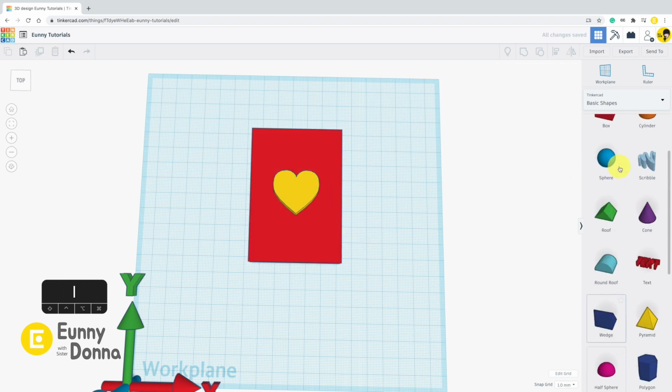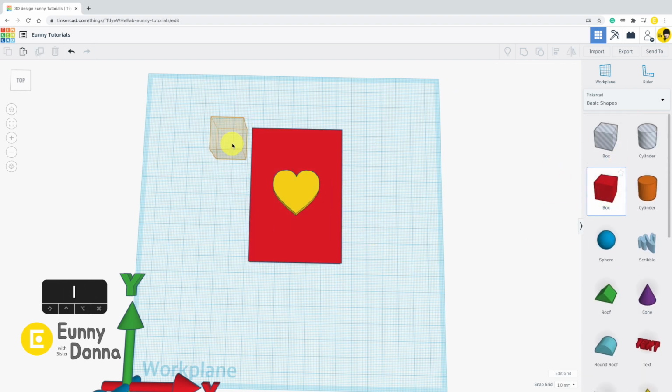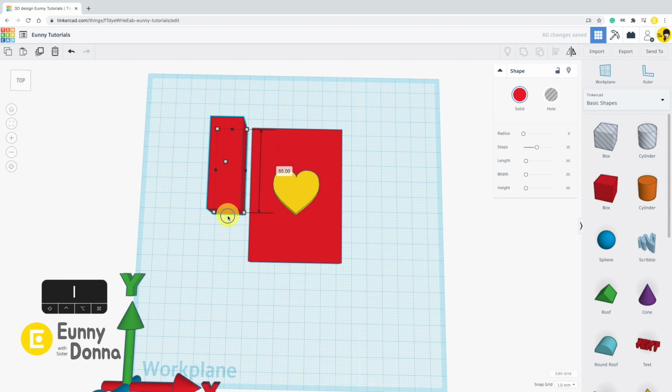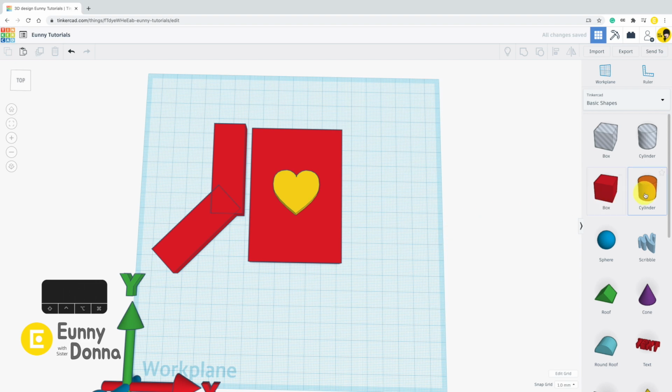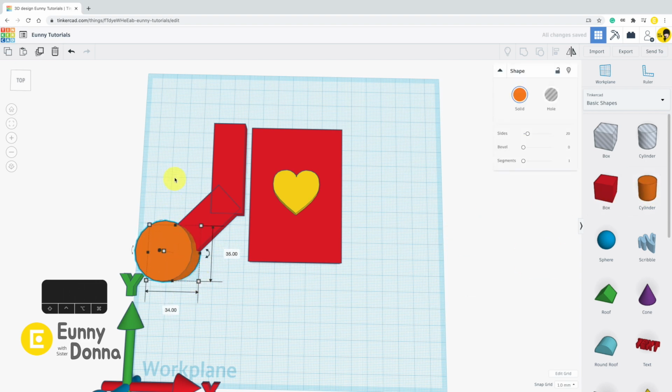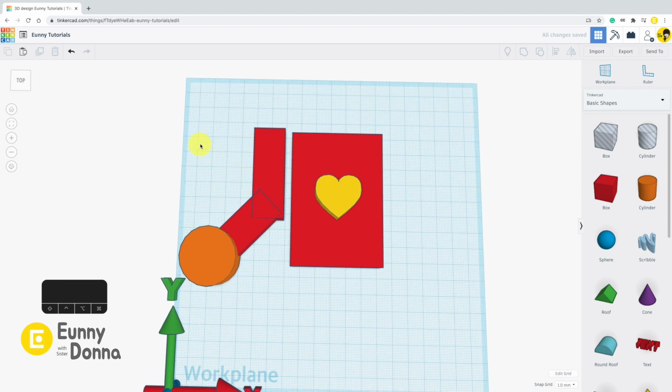In modeling, you may need to make reflected shapes, either vertical or horizontal. You don't need to make it again, but just copy and paste original shapes and reflect them with the mirror function. For example, I roughly made a robot arm shape here. Firstly, group these shapes.